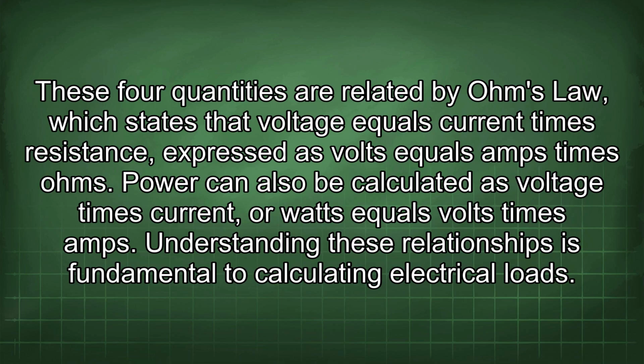These four quantities are related by Ohm's law, which states that voltage equals current times resistance, expressed as volts equals amps times ohms. Power can also be calculated as voltage times current, or watts equals volts times amps. Understanding these relationships is fundamental to calculating electrical loads.